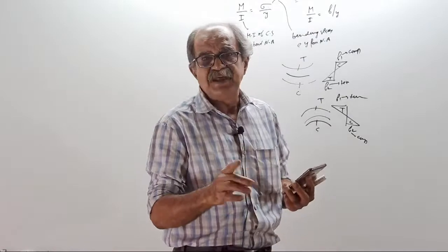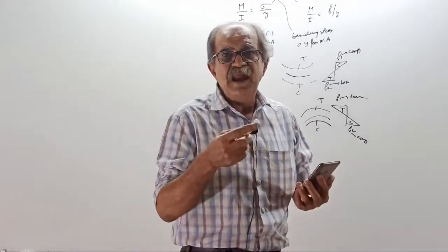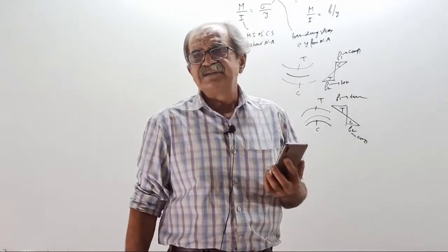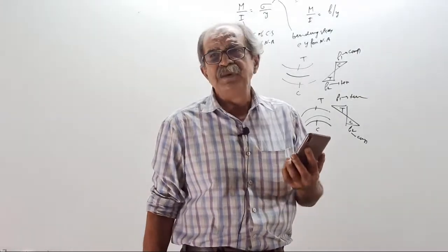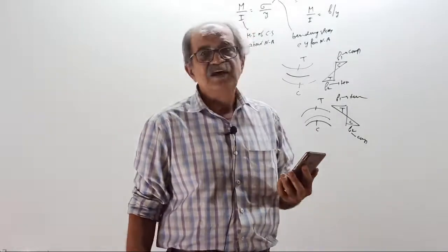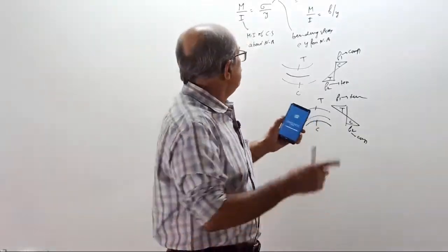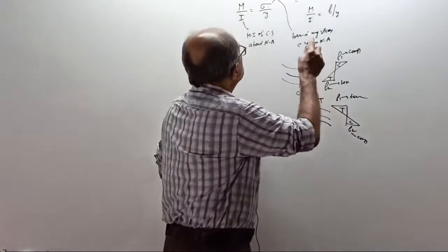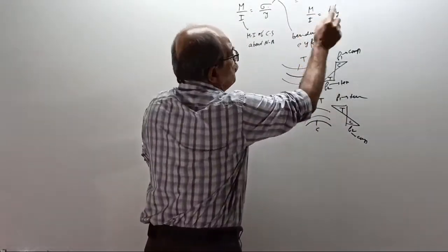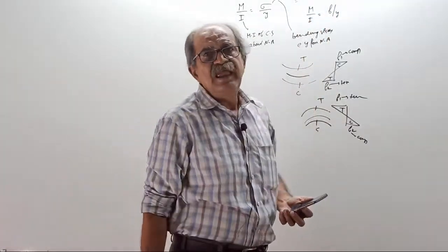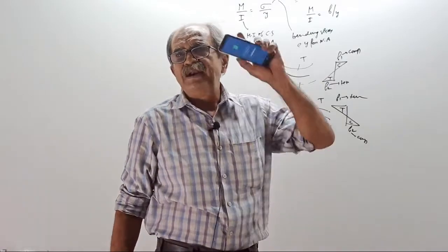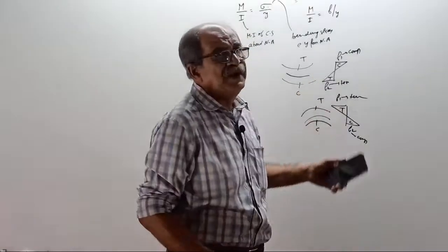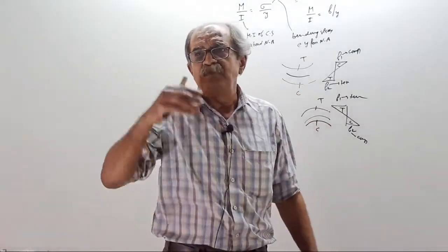How bending stresses are resisted by the cross section, I explained thoroughly in the class. Then, last class, I asked a question, somewhat what some people call a brain teaser. In the basic bending theory in strength of materials, you use M by I equal to F by Y. I is the moment of inertia. But in RCC, if you remember, we don't consider moment of inertia there. We go for some other approach.